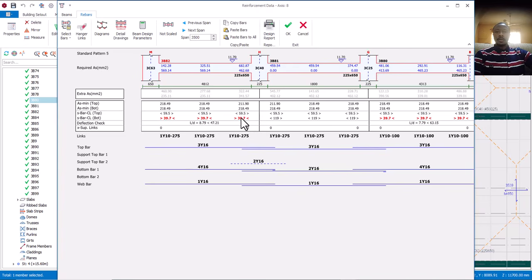And we have told you that since there is showing red, as long as that red is not less than 20, our structure is okay. Now, if you see that warning, the only area where you cannot ignore it is when all of this one is less than 20, and the number of reinforcement here is high. For example, you are talking of a 6Y16, 7Y16 or 8Y16 here.